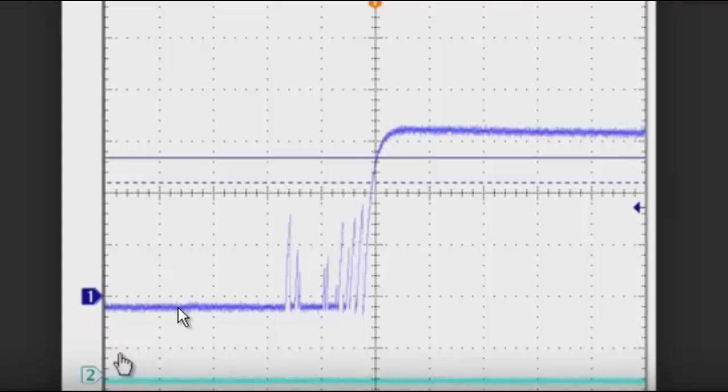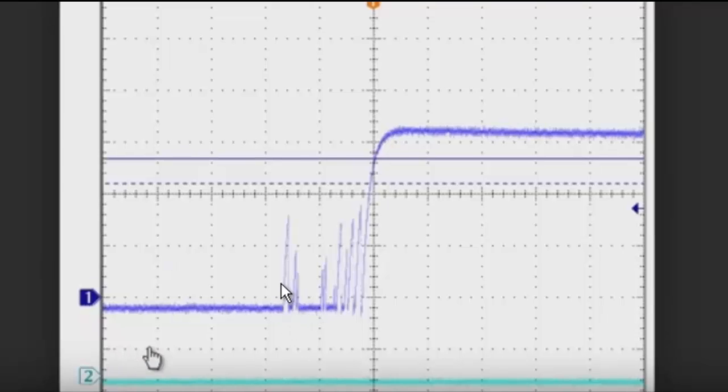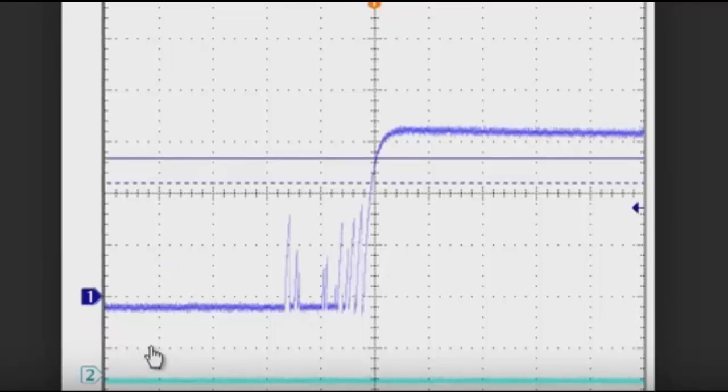Because our microcomputer is cycling so fast, it's reading a difference, and probably it will jump too high while the truth is low. We cannot trust a bounce in one cycle. To secure this, we program it in a way that we are not reacting on one cycle, but we react on a debouncing time of 50 milliseconds.